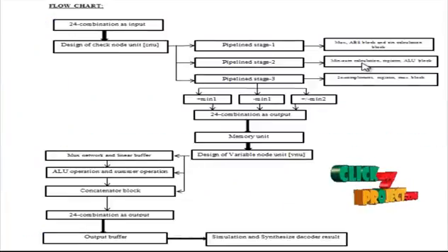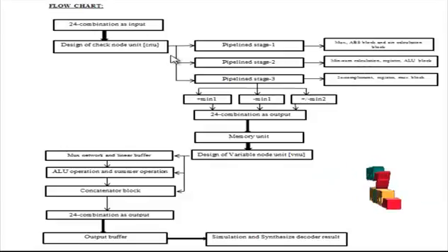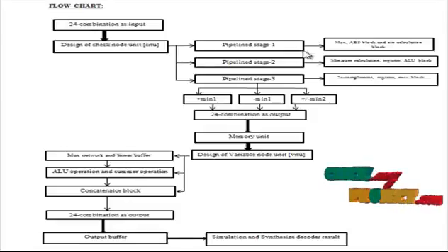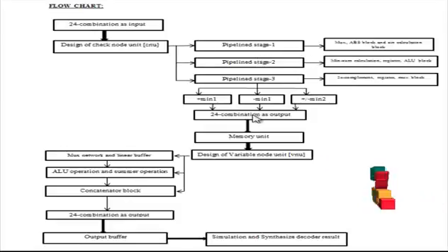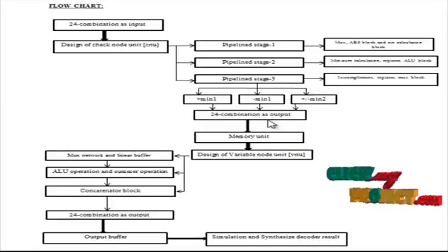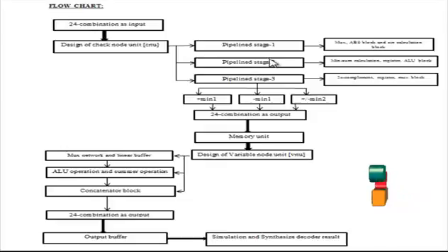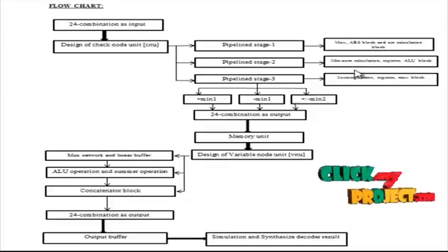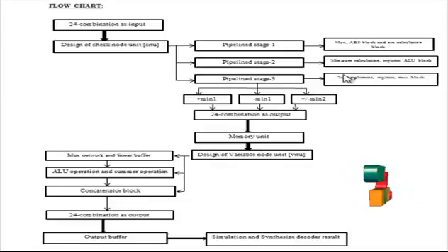Now we are going to discuss the flow of the LDPC decoder. The flow shows the full operation of the decoder. In this flow, the first module is CNU. CNU means check node unit. In the CNU, we can achieve 3 pipeline stages. Using these stages, we can provide the 24 combination as output, and the outputs are stored in the memory unit. The 3 pipeline stages are performed with the MUX network, register circuits, and min-sum algorithm blocks.